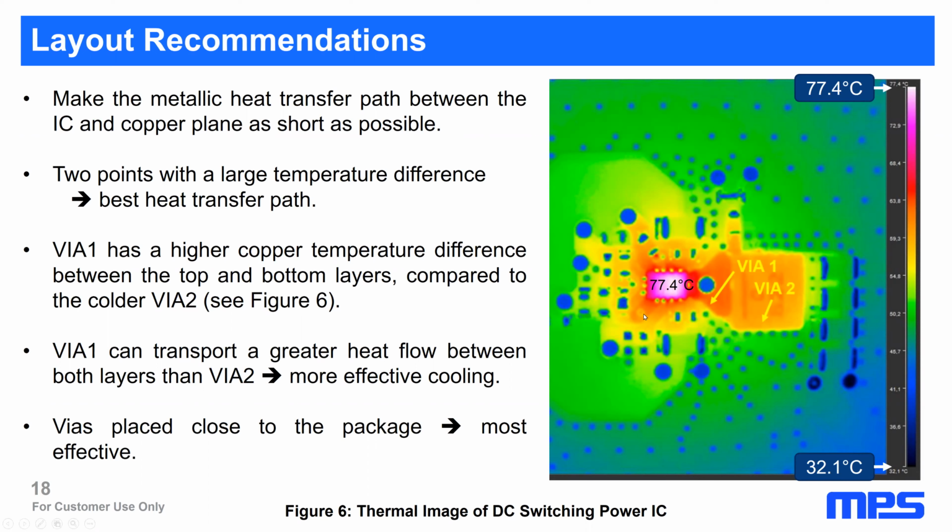For example, also here, these control pins, they are not connected to the MOSFET here. Make them also a little bit big when it's possible. It will additionally help to cool down the IC.